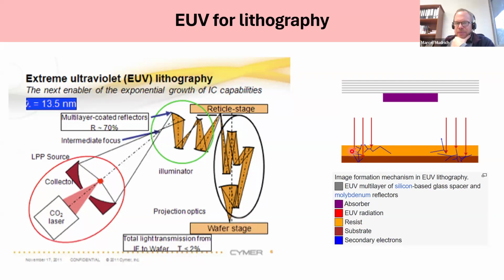That's a polymer which by irradiation by the EUV changes its structure, and then in a second step of etching and other chemical processing, the irradiated parts of this photoresist can be removed and then replaced by conductive and semiconductor structures, and in this way the microstructure can eventually be produced on the substrate.